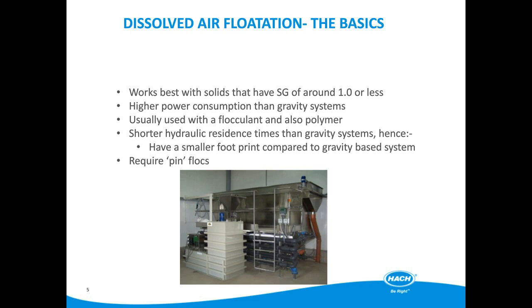When the DAF process is used as a first stage clarifier for reservoir water treatment, there is a distinct advantage in this short residence time, as algae do not have the chance to degrade and release their cell contents into the water. This reduces chlorine demand and the risk of taste and odour issues being created in downstream processes.